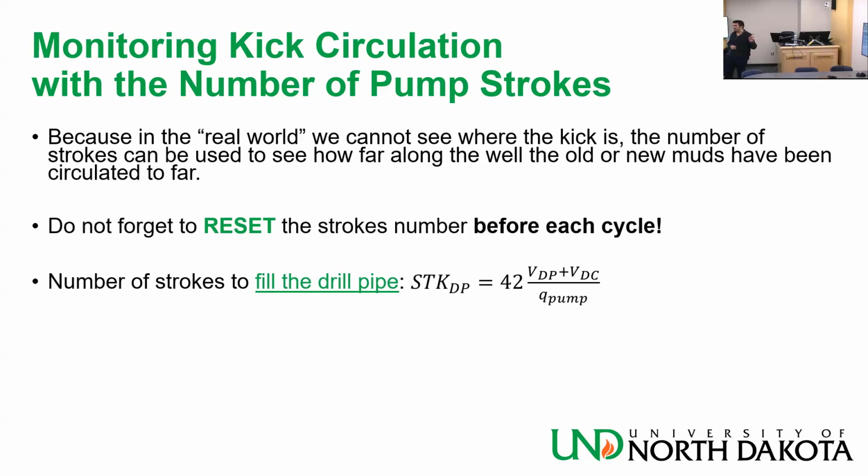If you use the equation sheet from the University of Texas that I gave in the useful resources document, it has the 42 in the denominator. It's wrong. This is how it should be. Just saying that if you use that equation, it has a mistake. So use this one. 42, you know why 42? No? 42 gallons in 1 barrel.